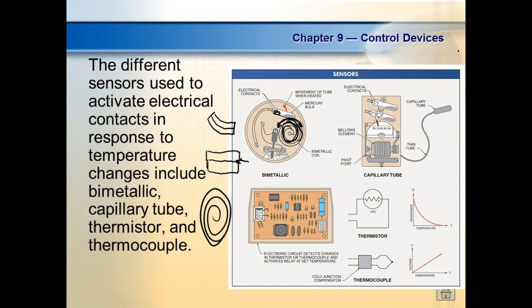So that's a thermocouple. So thermocouples, we use these. What's nice about thermocouples is they don't have to be electrically excited. They create a voltage that's proportional. The problem we have with a thermistor is that it's nonlinear. So notice a thermocouple, it varies its voltage, and look at the straight line. So anything that varies in a straight line, we say that's linear. A thermistor is not a linear output. So notice it does not vary in a straight line.